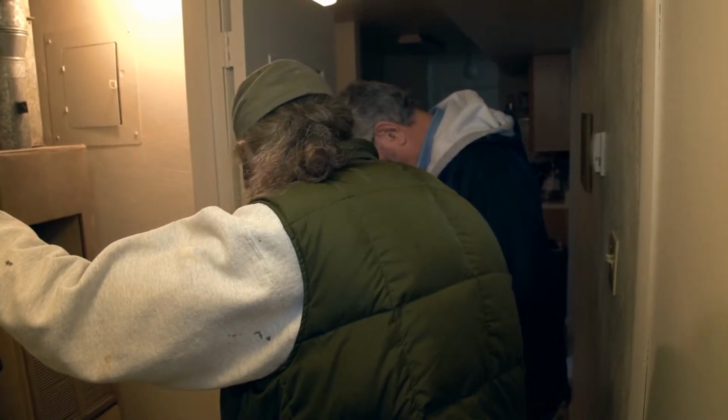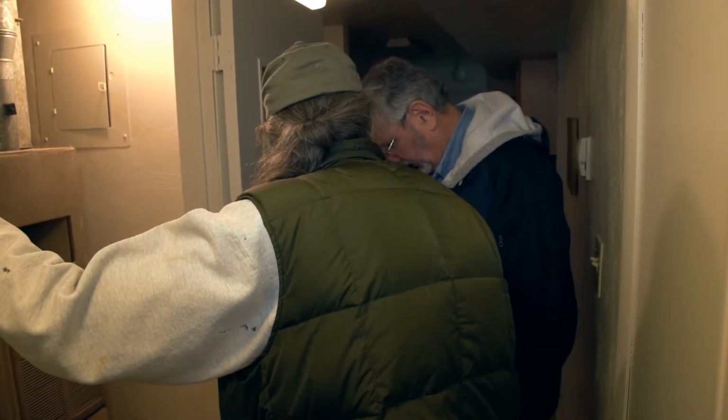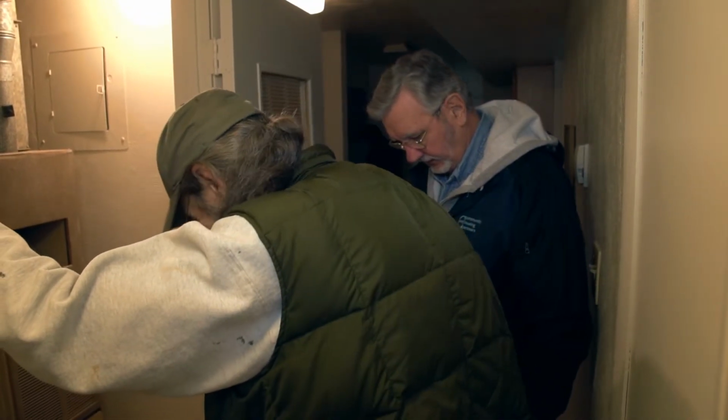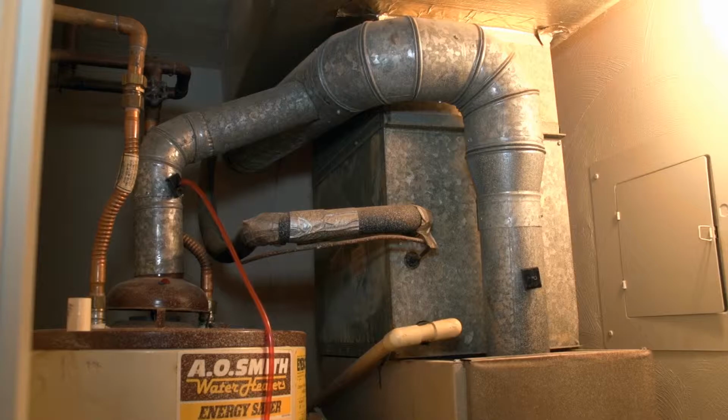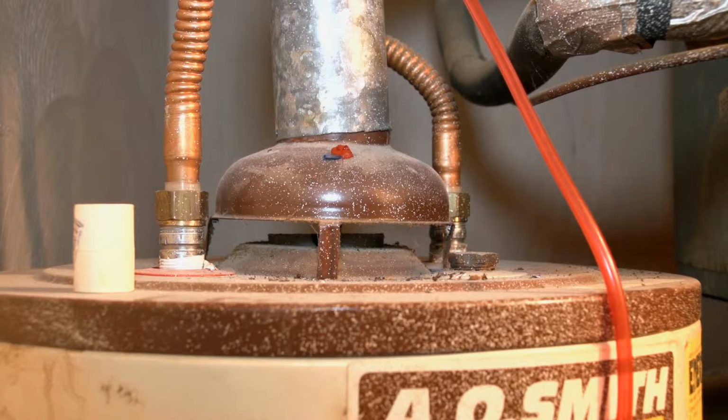Now, once we've established that all of our interior doors are in their proper setting, we can begin our CAS test. And we'll do that by coming into our CAS area, and we'll go ahead and fire up our first appliance. In many cases, what you'll see is a commonly vented water heater and furnace. This means that the vent stack from both the water heater and the furnace enter the same common chimney and exit the building. If that is the case, you'll want to fire your smaller BTU appliance first. That's usually going to be your water heater.